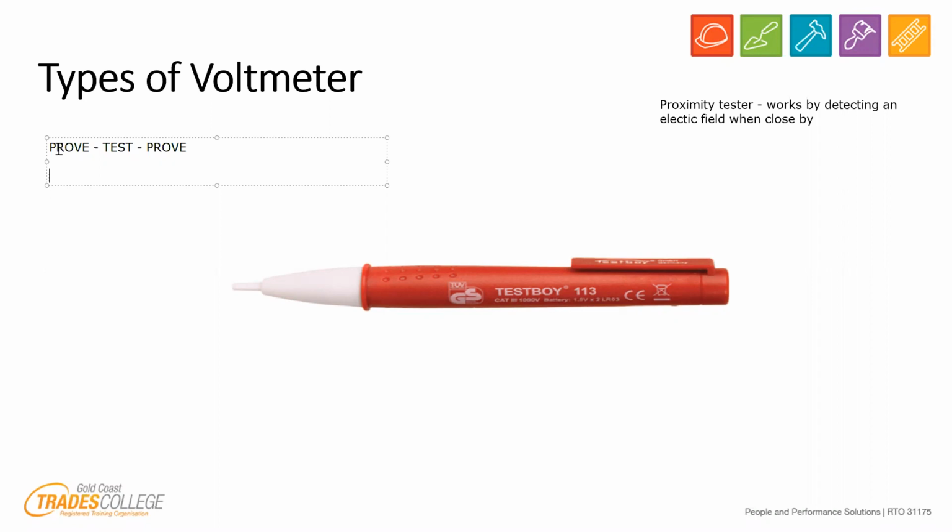With flexible cable, the cable is twisting inside, it's not straight through. So you might hold it up against an earth or a neutral, and depending on the tester, they may not light up. There's lots of different things, but most of the time it's because the batteries are flat. People think it's safe because they haven't followed this process. You're going to have accidents then.